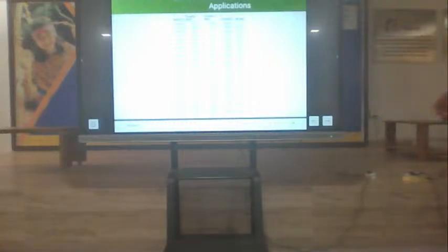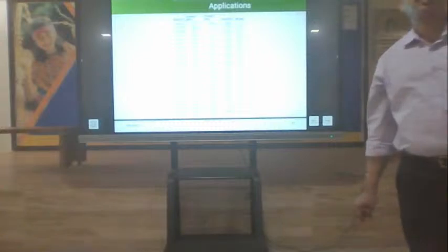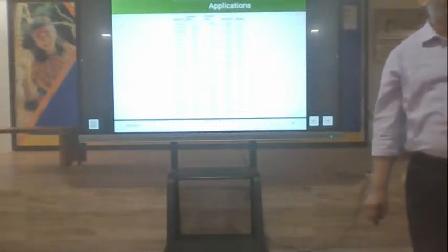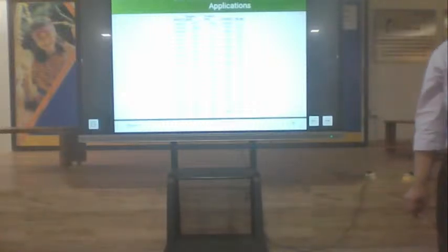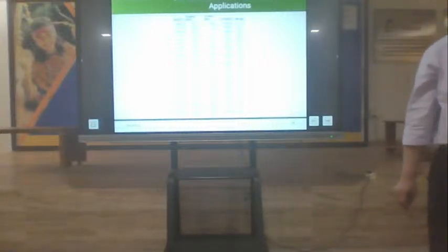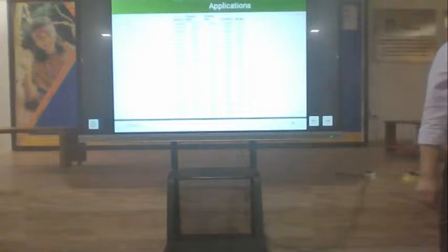Then there are other application specific circuits, your codecs and so on, which use 3.3. There are certain amplifiers in your laptop which use 5. So the input 12 volts has to get converted to the respective voltages. There are a lot of conversions inside.